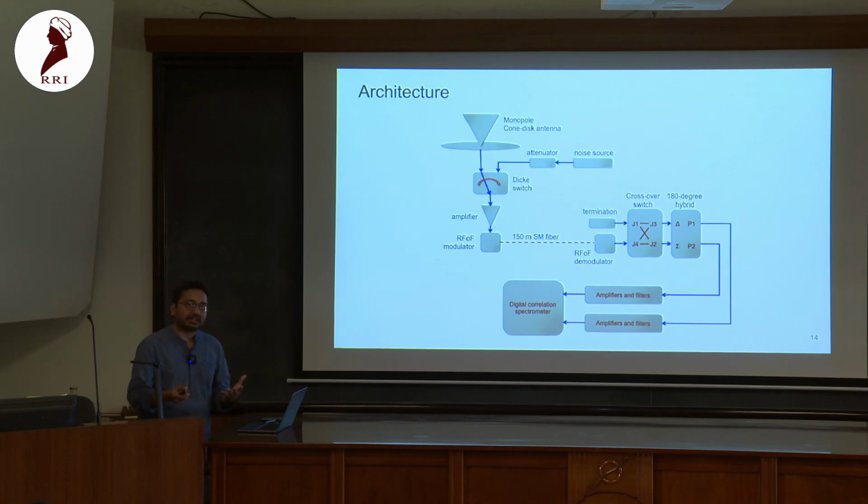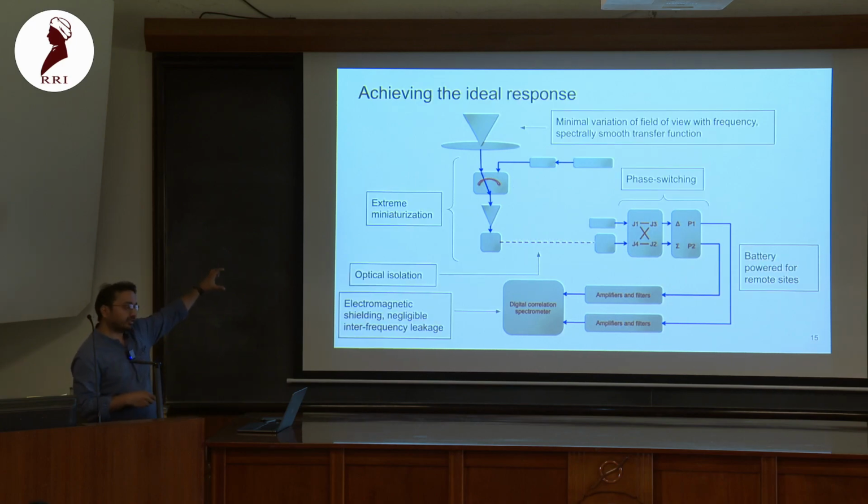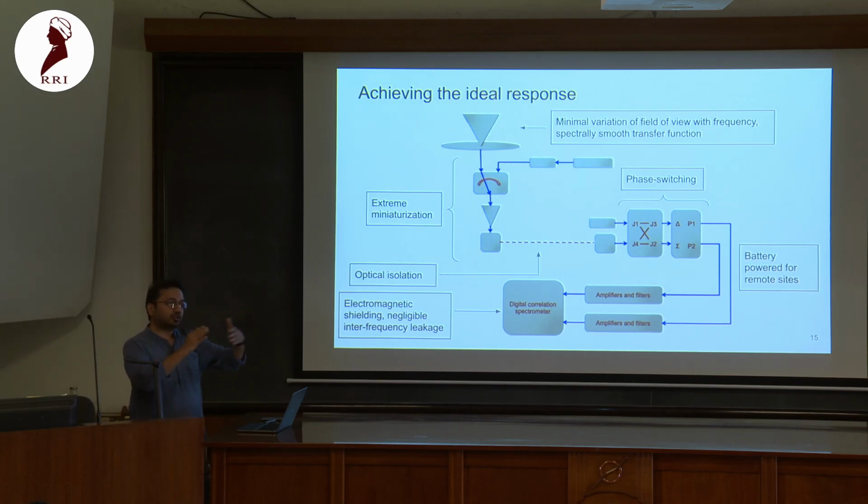We don't operate antennas in resonant modes, but rather non-resonant modes. And the impedance mismatch between antenna and the analog is what causes the standing waves. We really can't get rid of it, but what we want to do is minimize that. So basically we minimize the length that is there. So even if there is a standing wave, we are only sampling a very small part of the sinusoid and not a complete cycle. Because a complete cycle, again, spectral modes are there in the signals as well.